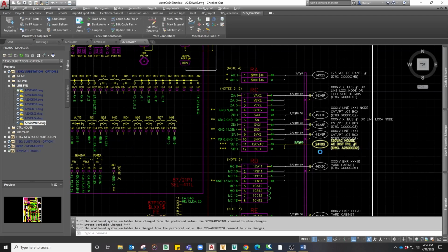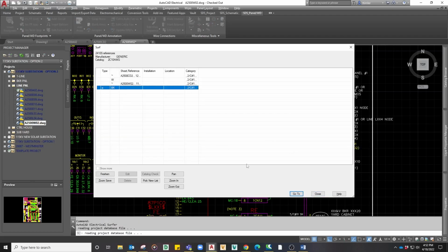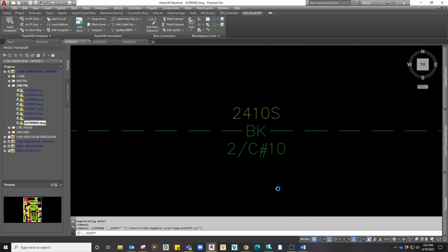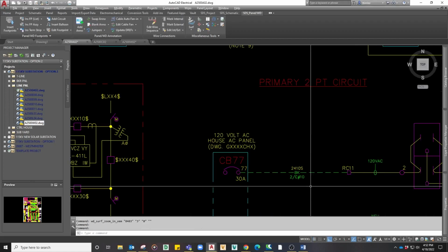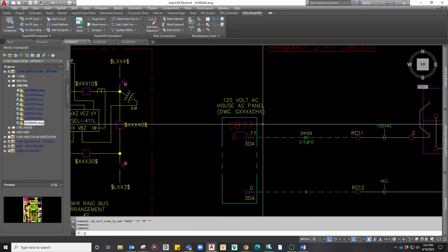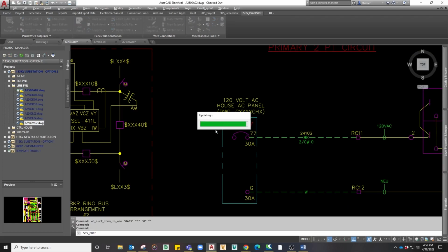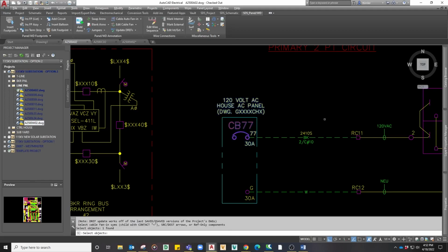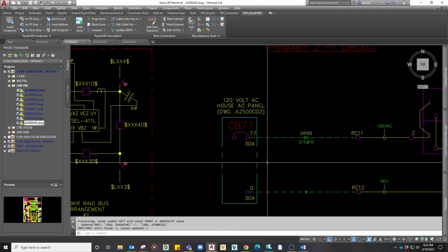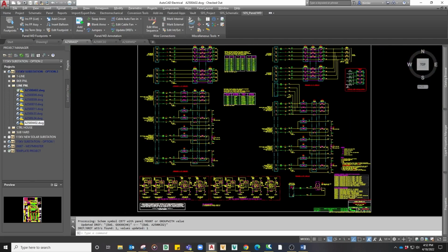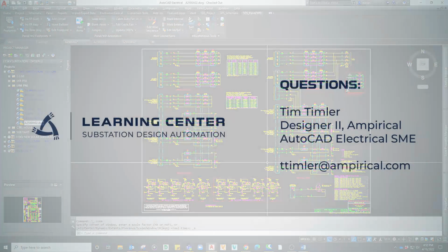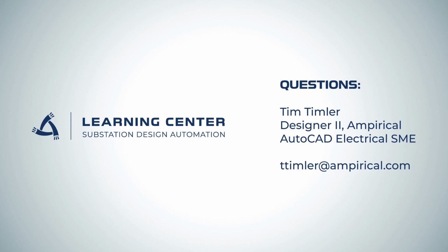I'll go ahead and surf on the cable instead here. So I'll surf back to the cable marker schematic parent, and I'll rerun the SDS deref command to get my panel cross-referencing information. Because that panel XREF attribute was already pre-filled with the drawing number, I get my CD2 connection diagram drawing number.